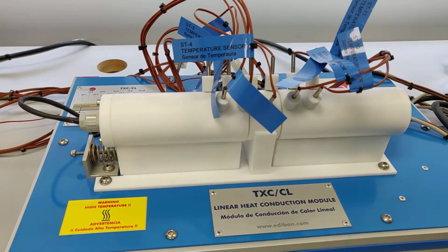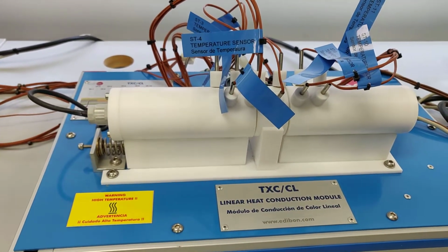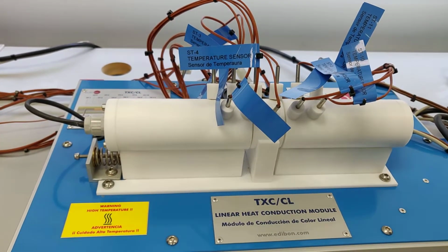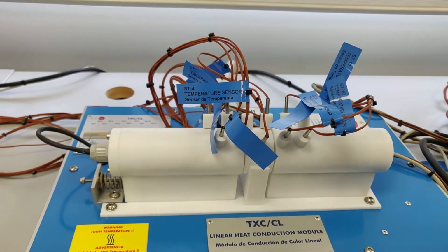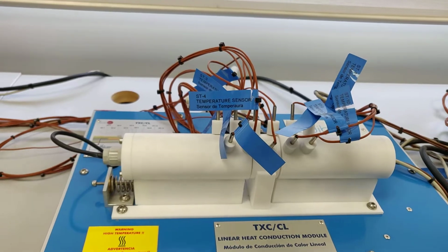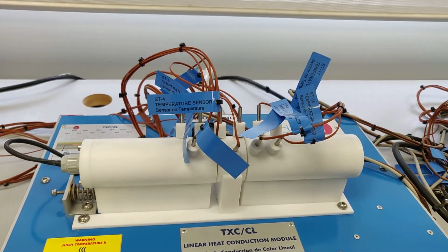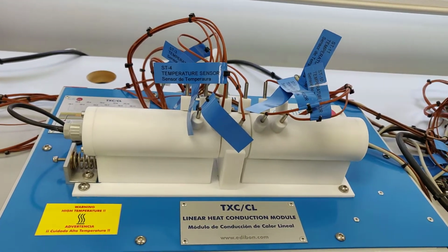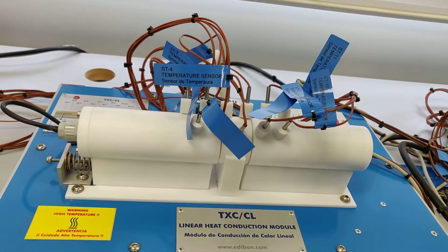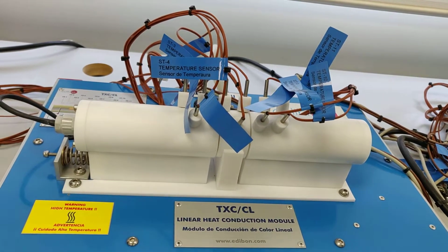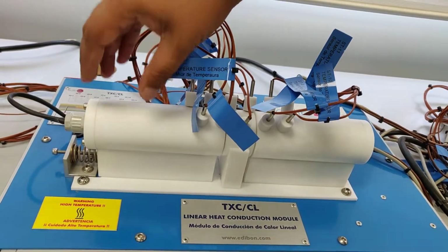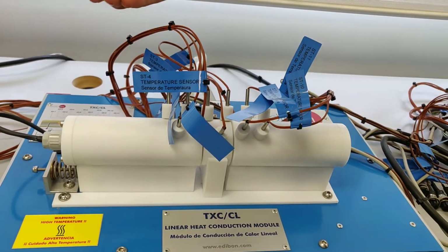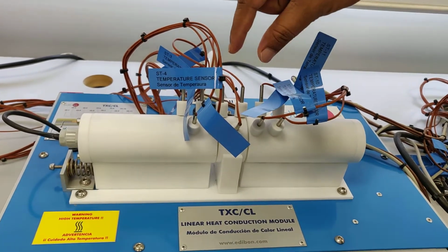So for the heat to flow in any direction, there should be a temperature gradient, meaning one side you should have high temperature, other side you should have low temperature. Only then the movement of heat takes place from high temperature to low temperature. This is what we have seen in thermodynamics and fluid mechanics, that fluids move from high pressure region to low pressure region, or the movement of heat is from high temperature to low temperature zone. So this side is high temperature and we are keeping this side cool with the water circulation system so that the movement of heat can take place through the test specimen.